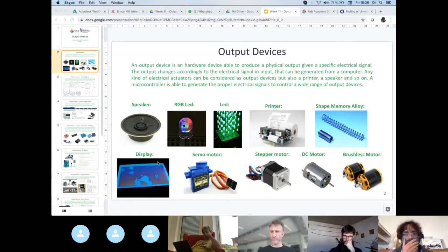With the display, you have the same consideration you have, for example, for the MP3 or for the printer. I mean, with the microcontroller, you cannot really have a lot of computational power. So there exist some displays that just have the pixels on or off, like this one that is displayed over here. And then they usually have lower refresh rates than the traditional displays, and of course, much fewer pixels.